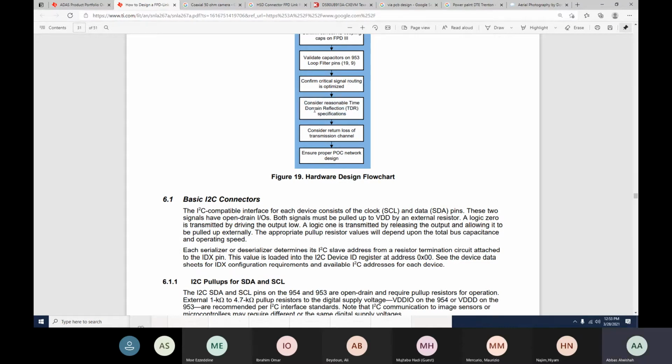And here you have the TDR, the time domain reflection. This whole system operates on either 100 ohm or 50 ohm. If you have a cable and you don't measure it before you use it on the system, and it's at, let's say, 38 ohms, and the system is working on 50 ohms, 9 out of 10 it will not work. And when I say 9 out of 10, the 10th is it will work, but it will give you an error message.